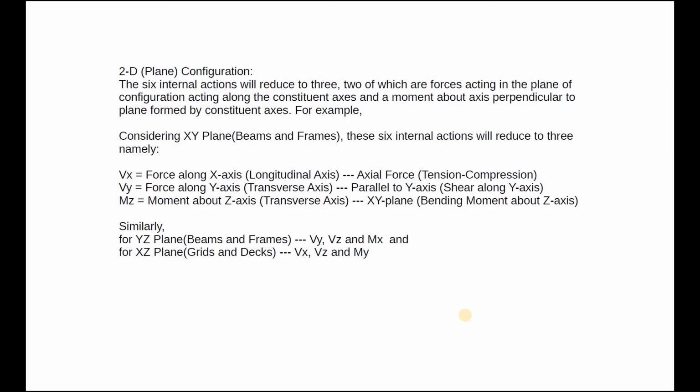Similarly, if the geometry is in yz plane, the rotation component is about the x-axis. And the force components are Vy and Vz. Similarly, for the geometry in xz plane, the rotation is defined about the y-axis, which is an axis perpendicular to xz plane.